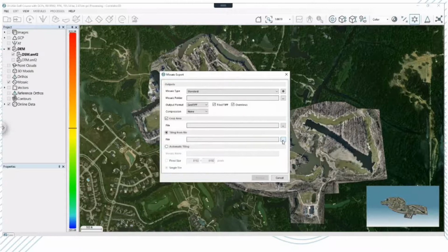If you just use automatic tiling, then all you're doing is telling the software, hey, start in the lower left or the upper right, I forget which one it is, and start tiling at a given pixel size until you've covered the whole image, and export those tiles. So visually pleasing, they may not be, especially when you're creating an overall layout map or something like that. So bring in a shapefile, create a shapefile and bring it in. You can also have the naming structure in there, and it'll read that. So it'll tile them 01, 02, or whatever you want, as opposed to automatic tiling.